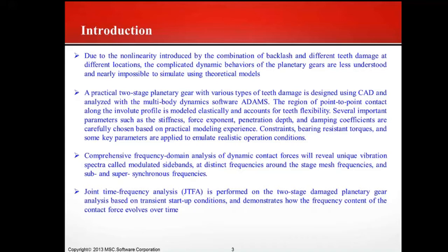For the other parts, temporarily, we just model them as rigid bodies, and we carefully choose the Adams simulation parameters for the constraints, bearing resistance torques, and some other key parameters in order to realistically simulate the gear transmission operation.